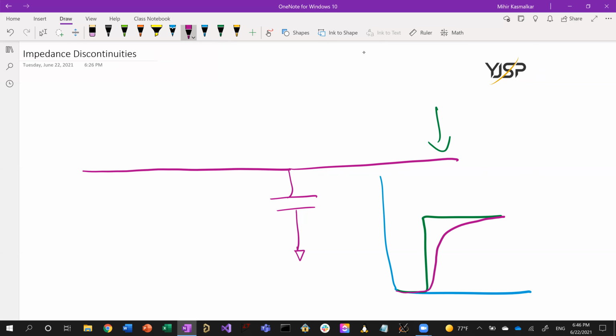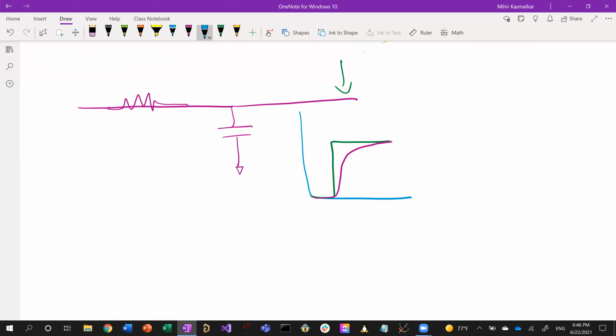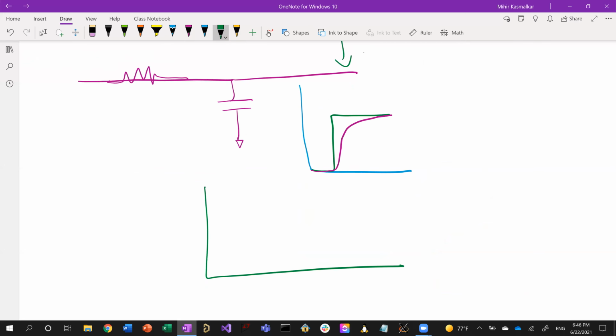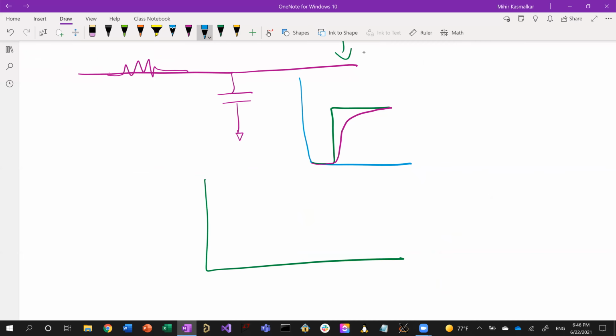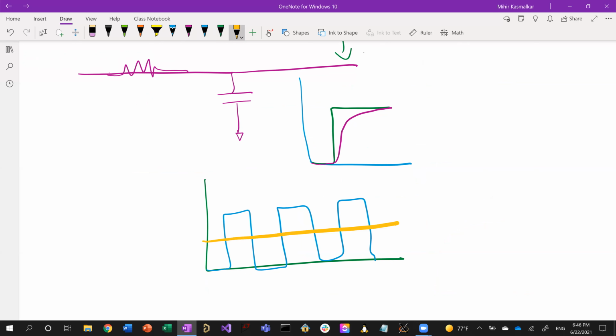Another way of thinking about it is it's acting as an RC filter, because you have some resistance here and you have this capacitor. So it's filtering out some of those higher frequencies. And remember, the way you make a square wave, you have a certain DC component, then you add in a sine wave at the fundamental frequency of the square wave.